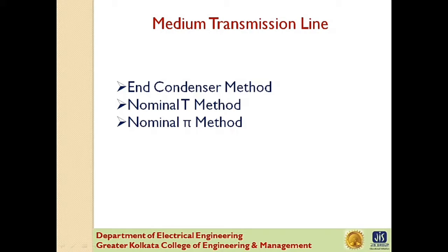The capacitance is uniformly distributed over the entire length of the line. However, in order to make the calculation simple, the line capacitance is assumed to be lumped or concentrated in the form of a capacitor shunted across the line at one or more points. Such treatment of localizing the capacitance gives reasonably accurate results.